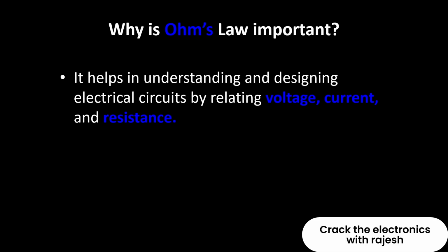You should know how much drop can be caused by a large plane area or by the stacked connectors we are using. That's why V equals I into R plays a major role. Any circuit follows Ohm's law.